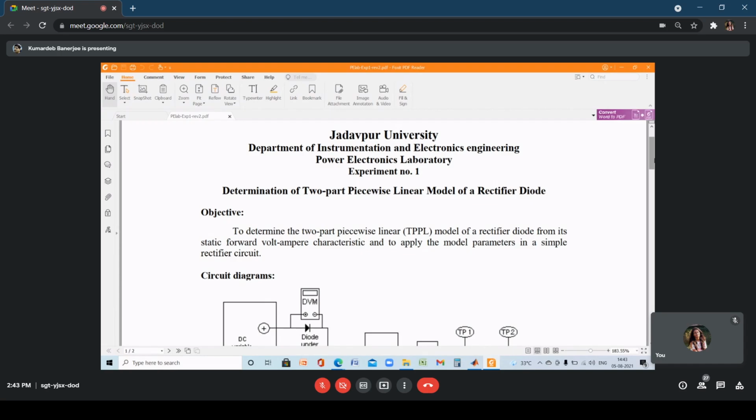So here what we plan to do is replace this by a linear equation y equal to mx plus c, that means if I know the voltage, I can immediately predict the current. Then circuit analysis becomes simpler. If I look at the VI characteristics of a diode, we find that there are two distinct regions. One is before V gamma, the cut-in voltage of the diode, and second is after V gamma, that means beyond the cut-in region.